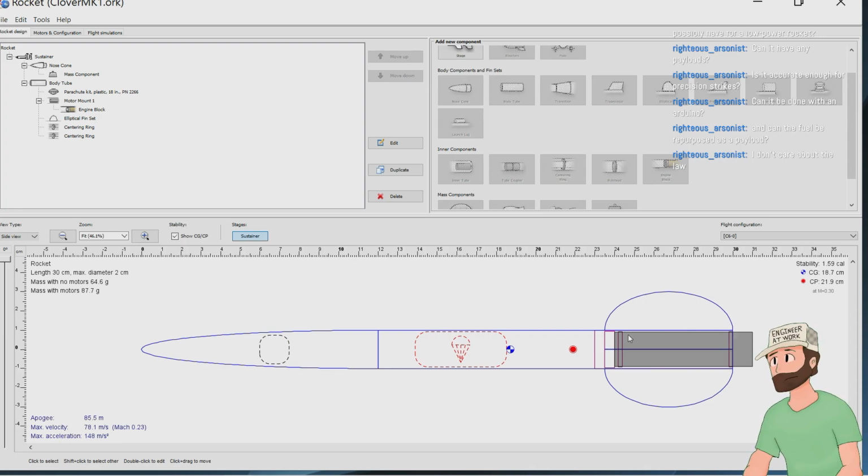And we basically just formed it as much as we could around this, while keeping certain manufacturing needs in mind. For example, this part right here is going to be basically a tube. We're probably going to put tape on the inside to keep the layers together, made of PLA. And this is going to be done in vase mode. And this one up here, we can probably print with thicker layers.